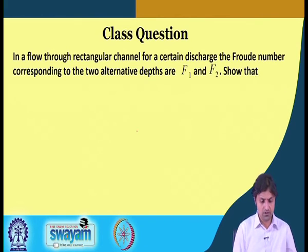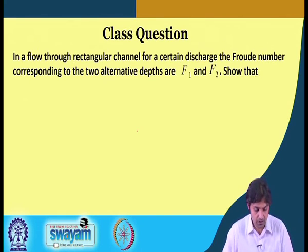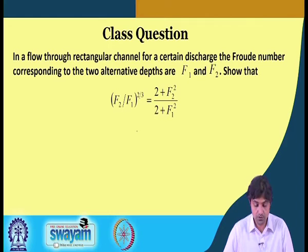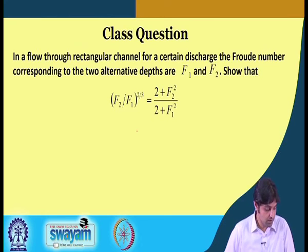There is one question: in a flow through a rectangular channel for a certain discharge, the Froude numbers corresponding to two alternate depths are F1 and F2. We have to show that F2 by F1 raised to the power 2 by 3 is equal to 2 plus F2 whole square divided by 2 plus F1 whole square. Is this a question related to the hydraulic jump?